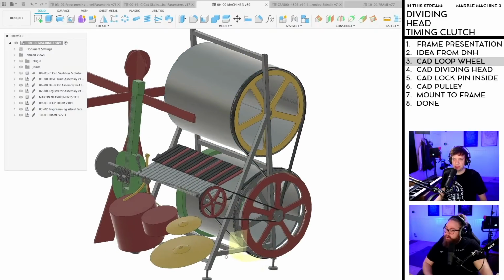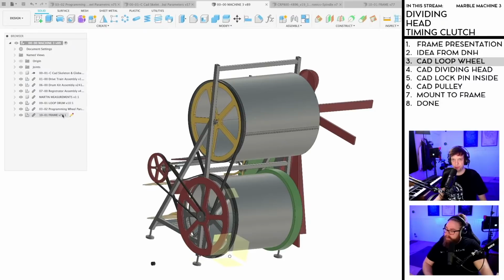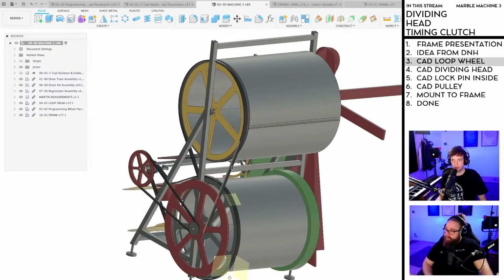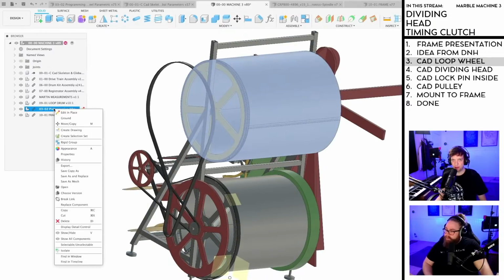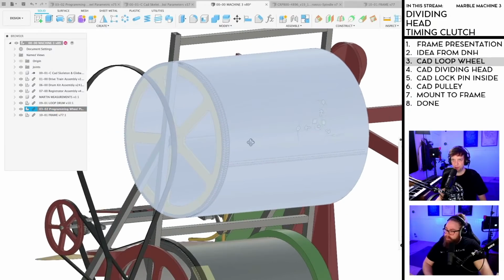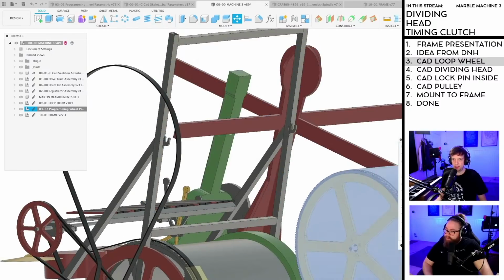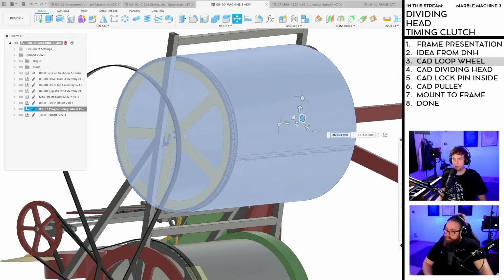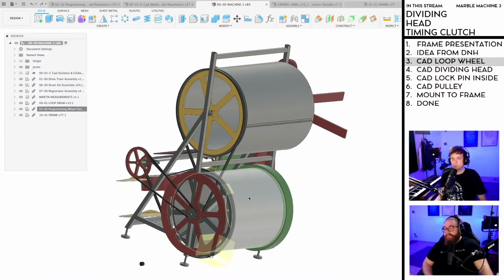So what this indexing thing will do is that we can make a setting so the two wheels are synced in all musical tempos. And since we're going to take these wheels off, the way we're going to do this is that we're going to take the belts to the side like this. And then we're going to lift the programming wheel just off like this. Take it away. And in here comes the new reprogrammed programming wheel, just slotting it in place and putting the belt back.